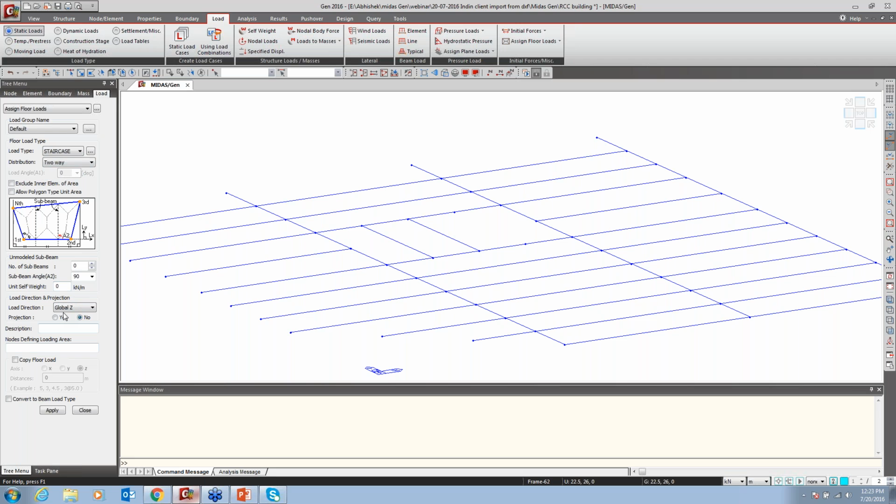Right now we are ignoring the slab stiffness, because a membrane slab doesn't have stiffness. Only the flat slab, being a plate element, has stiffness, and that is more stiffness. So for that reason we have to model that particular flat slab. It will help at the time of horizontal displacement also. That's why the flat slab and the membrane analysis procedures are different.